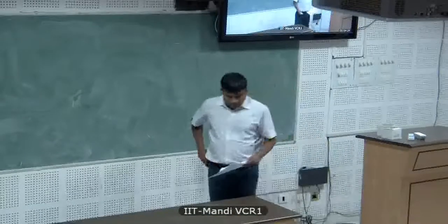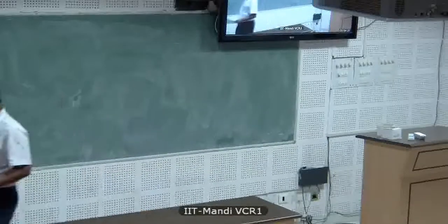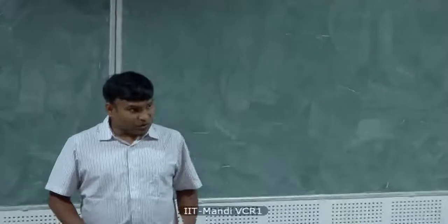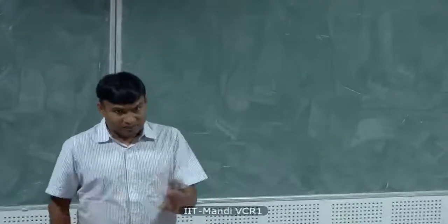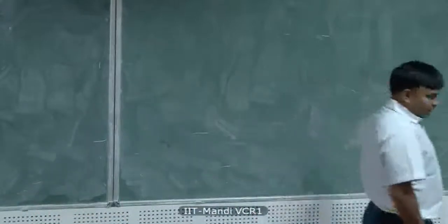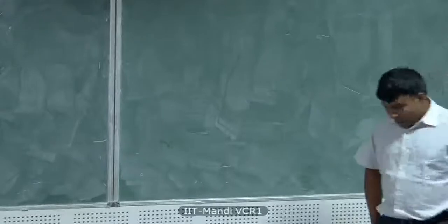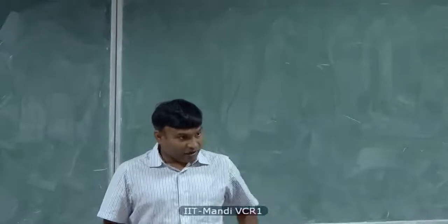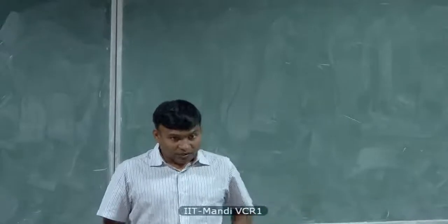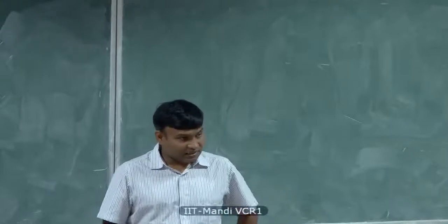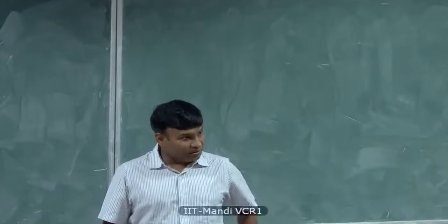Okay, let's just wait. So what we have to do this week is complete the code with cyclic prefix and a fading channel. That shouldn't be too difficult, and you can do it for one OFDM symbol and put them in a loop. And what I want you to do is, I'll give you a MATLAB code for a convolutional encoder and decoder of an arbitrary coding rate. You integrate that code with your OFDM transmission and get the results with channel coding.